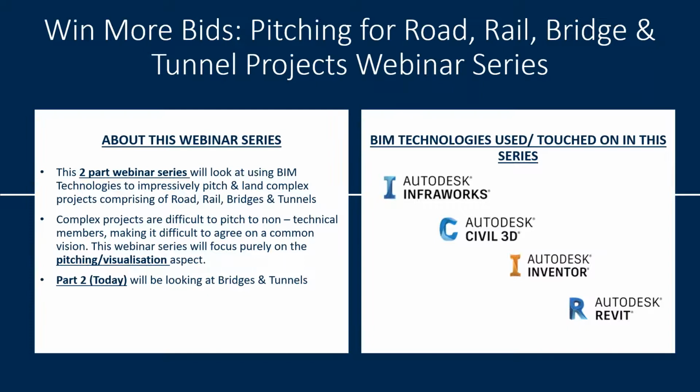The focus of the infrastructure elements were road, bridges, tunnels, and rail. And the technologies that we're going to be touching on in the series were Autodesk Infraworks, Civil 3D, Inventor, and Revit. Infraworks is the star of the show, the reason being that it is the easiest one to use from an adoption perspective. I didn't want to give you something too complicated to jump into and feel overwhelmed. Civil 3D, Inventor, and Revit form part of the detailed design process, so not necessarily the pitching phase of the project. However, I have included them to show you how, once you have pitched and won the project, you could integrate it into your detailed design, which I'm going to show you the workflow of in a bit.